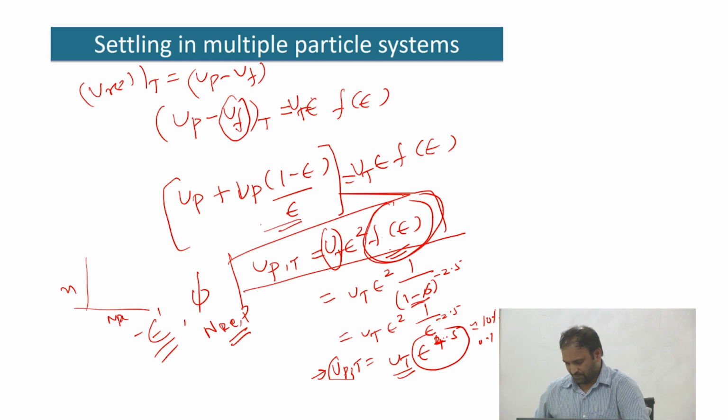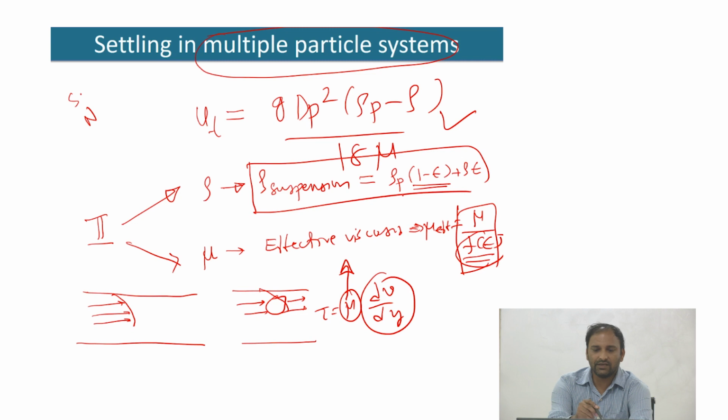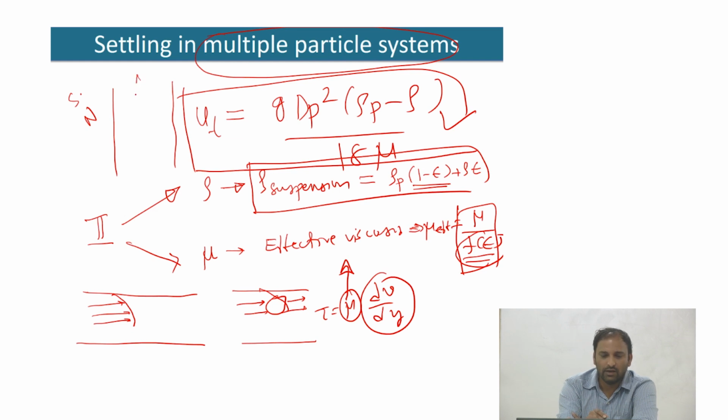That's because all these expressions that we developed, the Newton's regime, the Stokes regime, everything, are typically applicable for cases where you have a stagnant fluid. Say that you set a particle into motion by gravity; in that sense your fluid is still stationary, there is no net flow of the fluid as such.